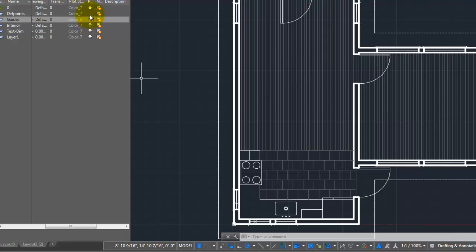The next icon you see is a little printer icon. Okay? That little printer icon will determine whether this layer is seen when you go to print or not. And since this layer is going to be used as guides, right, it's a perfect layer not to be shown when we print. Right? So anything that we draw on it isn't going to be showing up down the road. So I've gone ahead and I've clicked the little printer icon, and you see when I click it, it gives me that little red circle through it. That means it's a non-printing layer. So when I go to, say, File, Plot, and I go over to the big plotter and I plot this drawing out, these lines won't show up. Right? So it's a really useful thing to have.